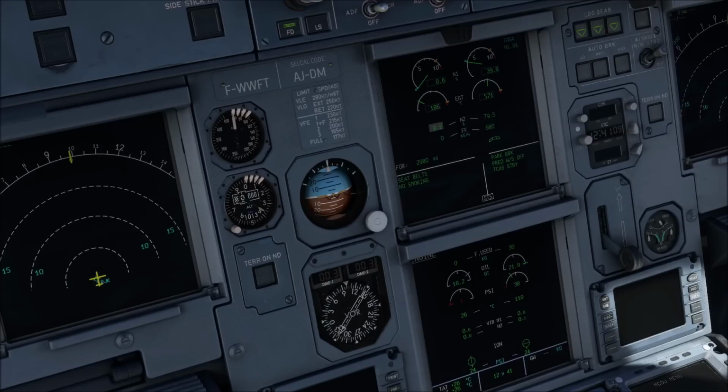Okay, now the pressure has dropped to 24 psi, so let's increase thrust a tiny bit more, just to be sure that we actually get sufficient pressure. This would have to be coordinated now with the ground guys, since we are using more than 40% N1. It is permissible, but you have to be careful. As you can see, we just need a tiny bit more, so that is totally acceptable for us. And engine number 1 is starting.